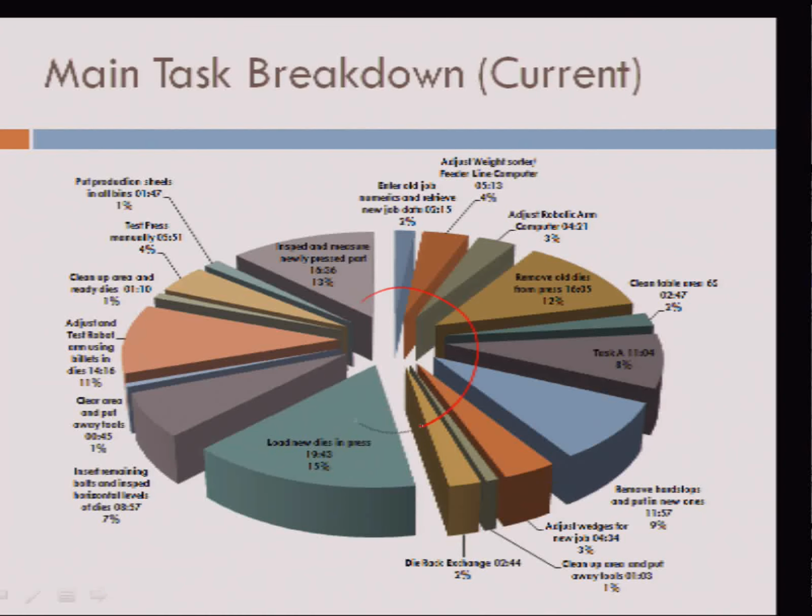So this is now more detailed analysis, and again depending on where you apply tooling analysis, depending on where you apply direct time study, these appropriate categories of major activities will be obvious. The big thing is that you need to have this data, because it is only when you have these time values for key operation steps in the current state process, and then you record in the future state, the proposed process, the same time elements, you can do a nice non-parametric comparison of the two states, and then come back and see if the improvements you made have a significant impact on the total change over time.